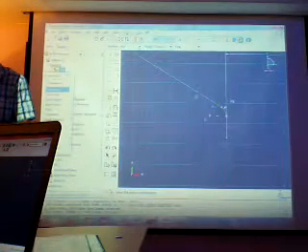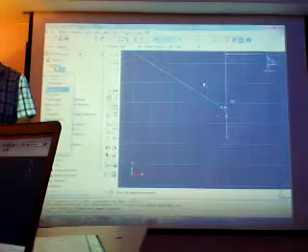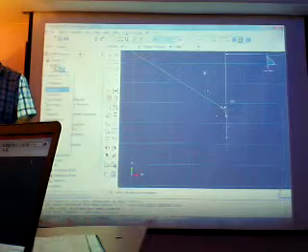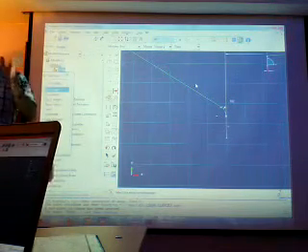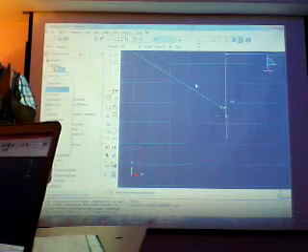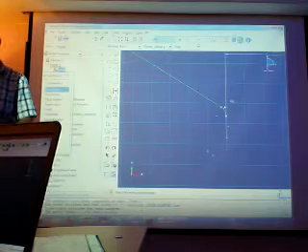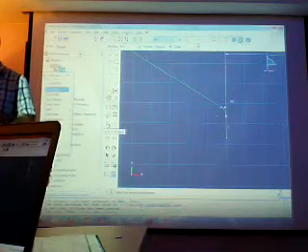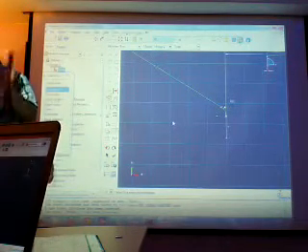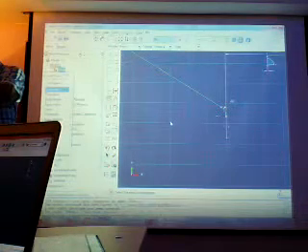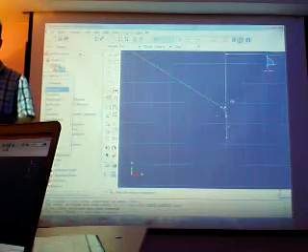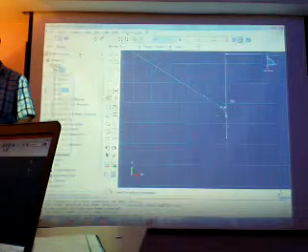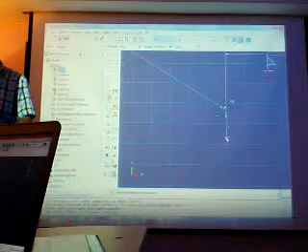The color in the sketch also shows the constraint on the part. When it's green, it means it's fully constrained, and that's okay. If it turns purple, it means you have an error in your constraint. When it's yellow, it means you don't have enough constraint. It's not important to always change the color to green, but it's important to take all of them away from purple.